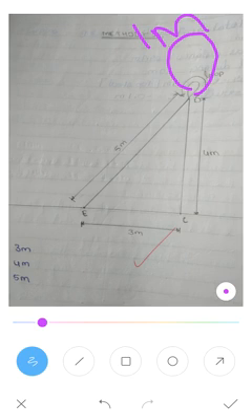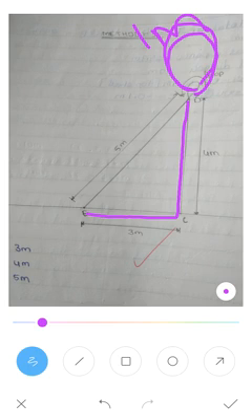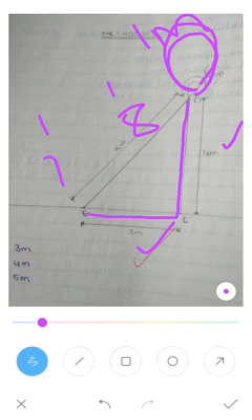Okay, first the tape goes for 3 meters, then it runs approximately perpendicularly for about 4 meters, and you hold a 1 meter loop. This length should be 1 meter. So 3 plus 4 is 7 meters, so 7 meters and 8 meters of length will be there now. One after the other you hold it and make one loop.